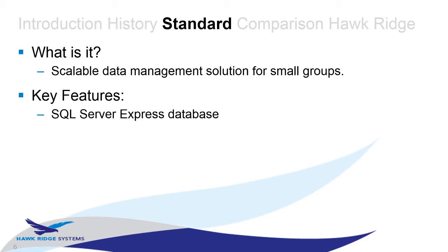The baseline model that we like to follow or recommend as best practice is if your company is below 5 users, so between 1 to 4, you can definitely get away with using PDM Standard with the SQL Server Express database in terms of performance. But once you start hitting 5+ users, that performance will start to show a lot more because you're having more concurrent usage, you're hitting that 1 GB of RAM. Because remember, this database server is live updating and running all of these transactions all of the time.